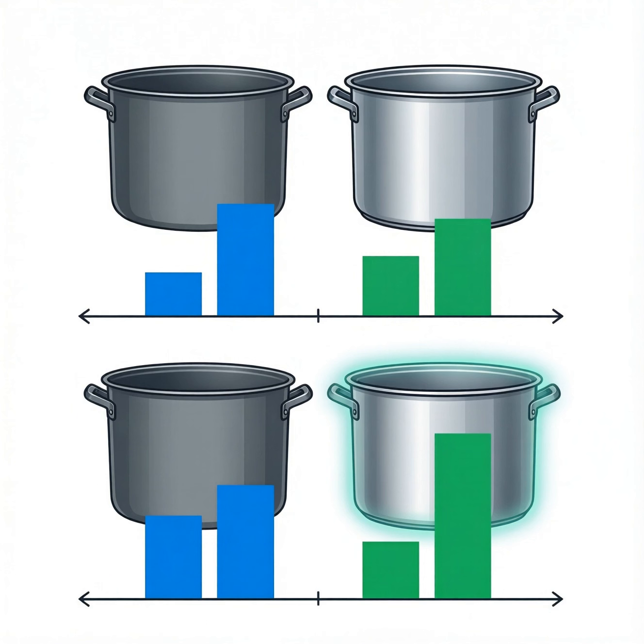tools. When you stir a pot, the metal surface begins to vibrate, converting kinetic energy from your spoon into audible sound waves. The frequency of those waves depends on the pot's material density and stiffness, which determine how quickly it can flex. Steel, with its higher modulus, resists deformation more than aluminum, so it produces a sharper, high-frequency clink. Aluminum's lower density allows the walls to flex more easily, yielding a deeper, resonant tone that lingers longer. Pot thickness adds another layer of control.